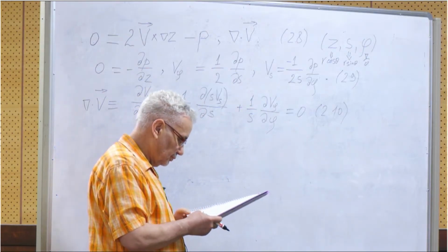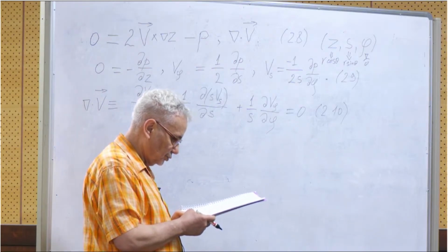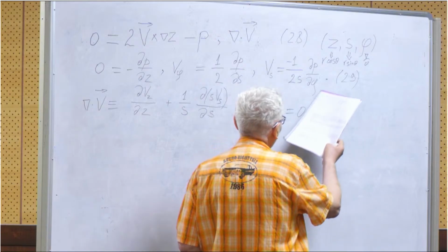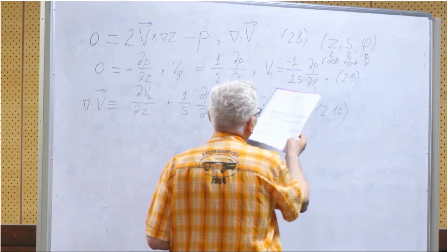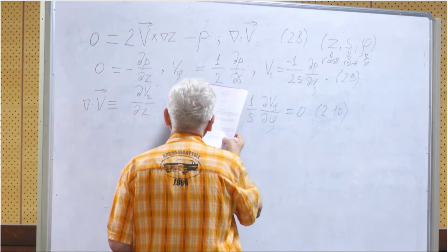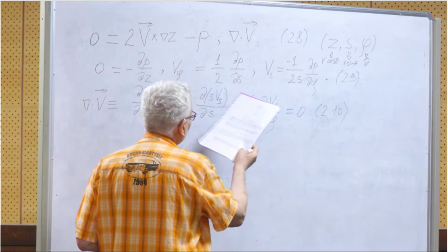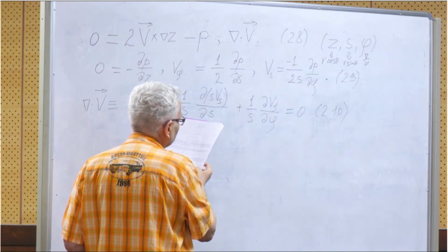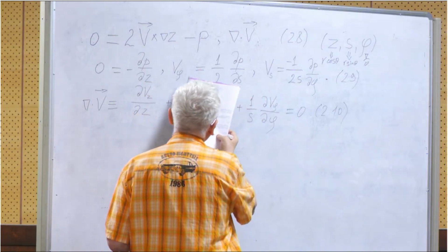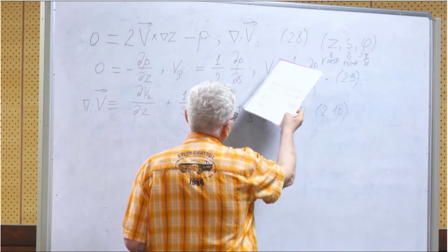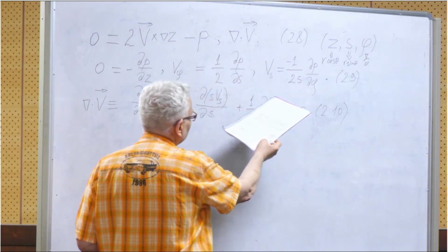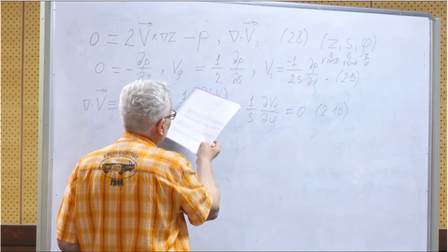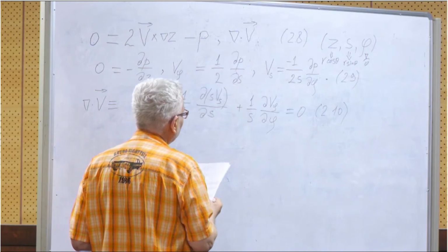So substituting the velocity components expressed through the pressure from 9 into 10, we have two velocity components, which we can express via the pressure and then put in this equation. So we have Vs, which is represented directly from the pressure, and V phi, which is also represented directly from the pressure.